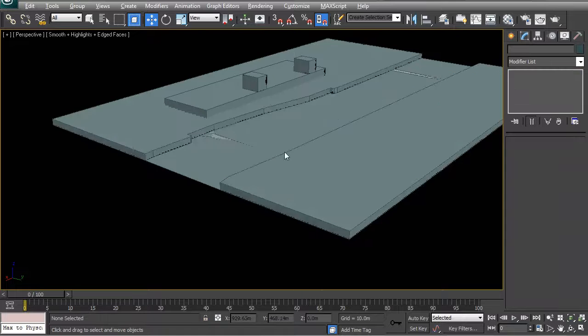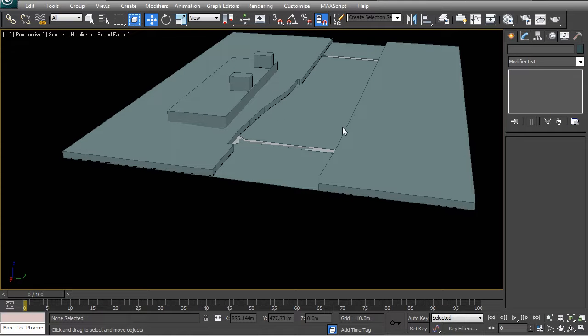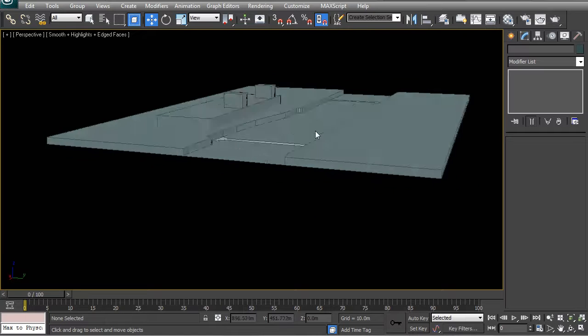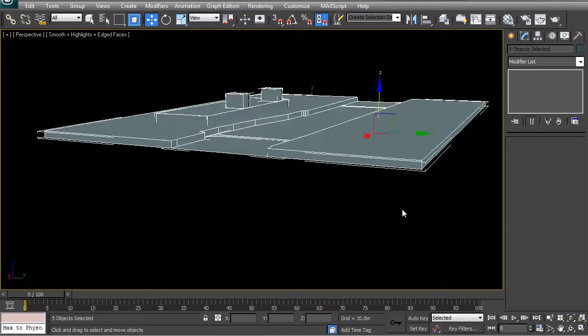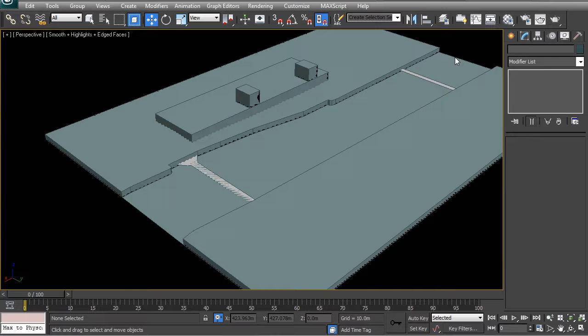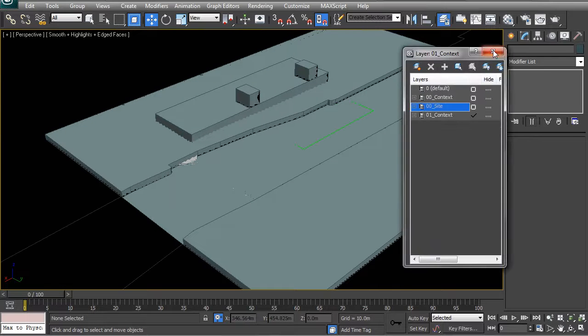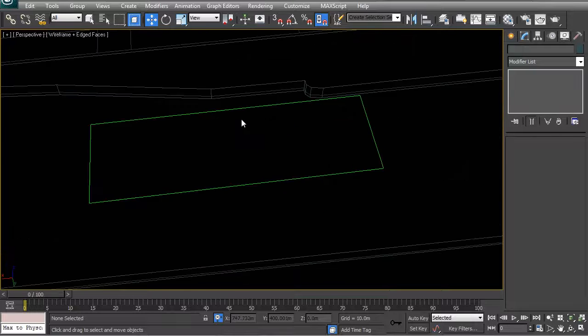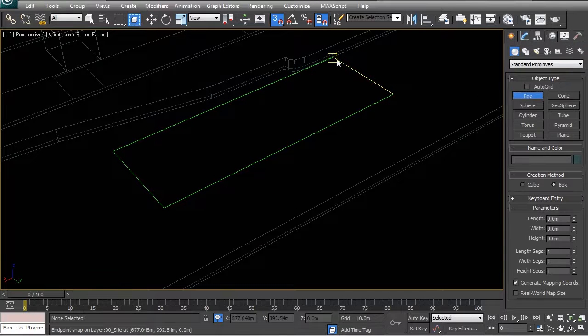In my case, I know that the barge will be floating just above the water, so perhaps it's 1 or 2 meters above. So it would be a good idea for that ground surface of that barge to be our 0 level. That means that I would ideally want to take this entire model now and move it downwards by 2 meters. So let's go and quickly do that. So we type in -2, and then you'll see that once you draw in your barge, so let's just go in and very rapidly do that.